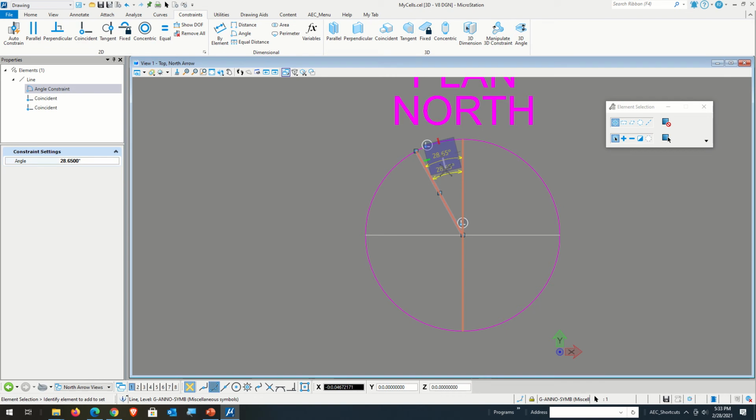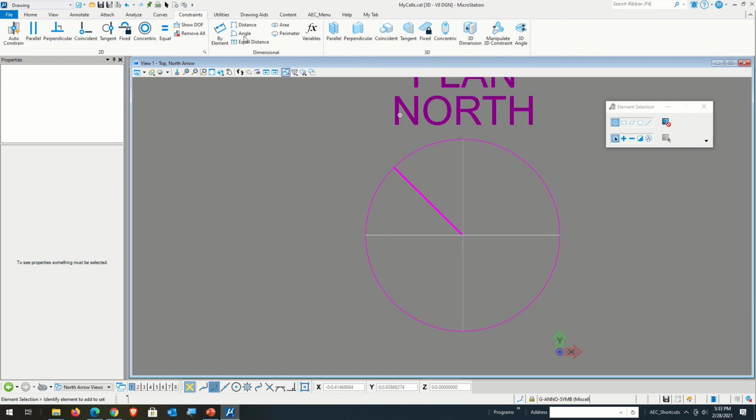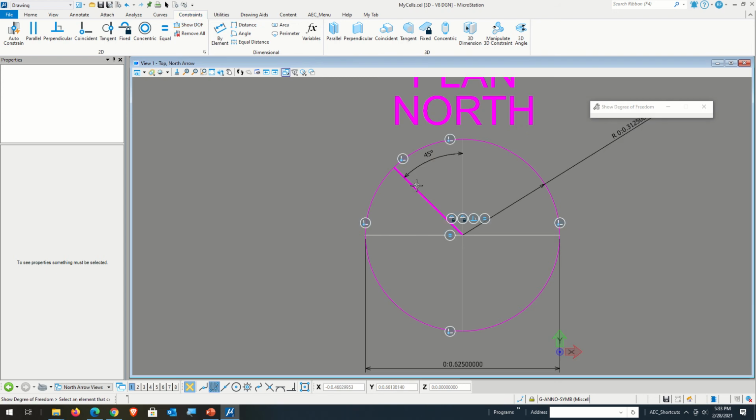let's say I set that to 0 or to 45. Come on. Oops. I edit. If I set that to 45, there we go. So yep, I can rotate that. Let's see what the degrees of freedom are. 0. Okay, so this thing here is now pretty well locked down. But they really want to make this either 0 or 90, right?